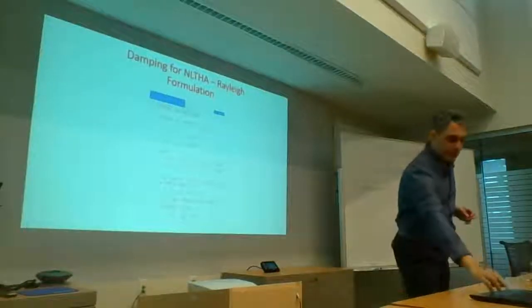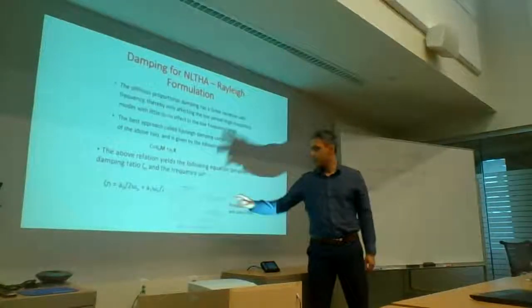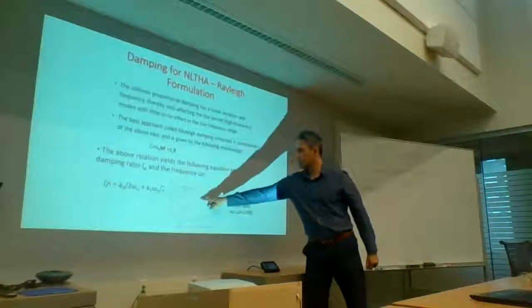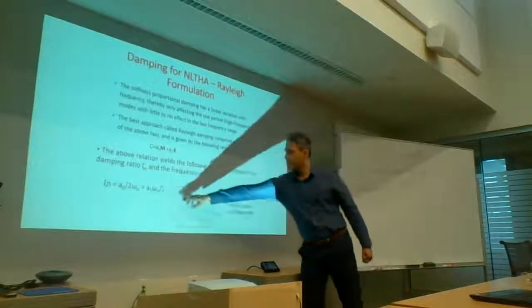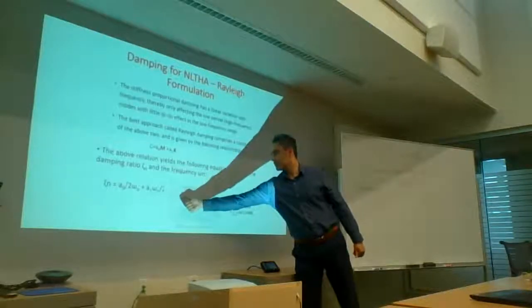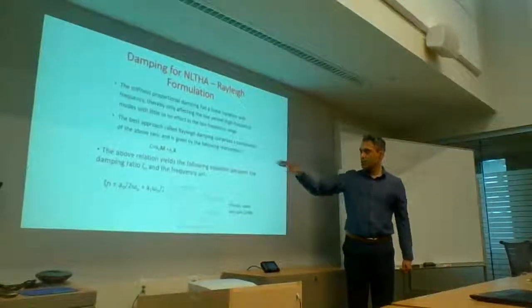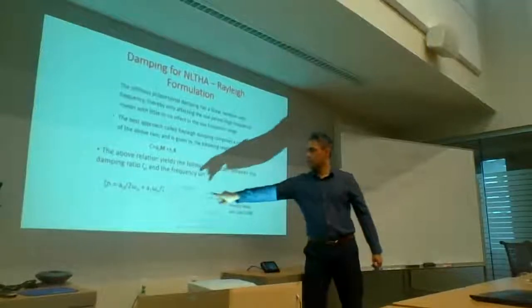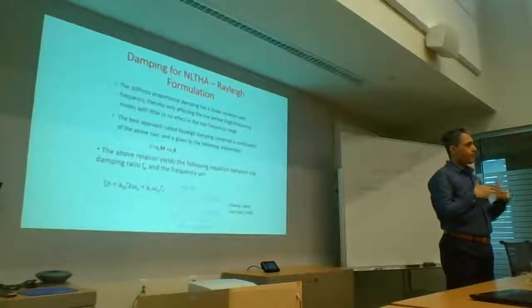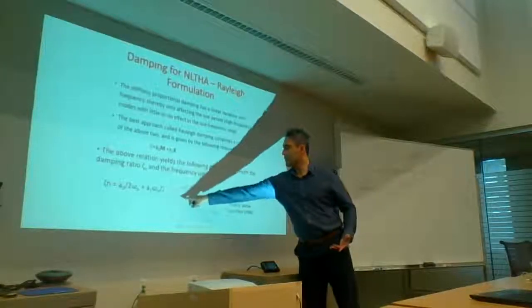Okay, so then this curve here is anchored to that value. So you see how the damping is changing. But at this point and at this point it's the same. So one modal period is over here, the second modal period is over there. And we play with the A0s and A1s relative to the omega n's to make sure that at this period and this period, we're matching the damping appropriately. Everywhere else, you're underdamping or overdamping. So between these two periods, you're underdamping.